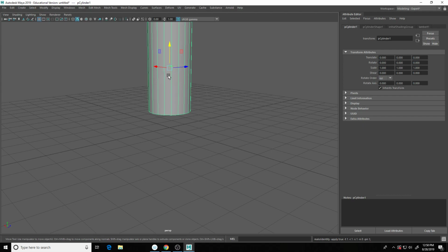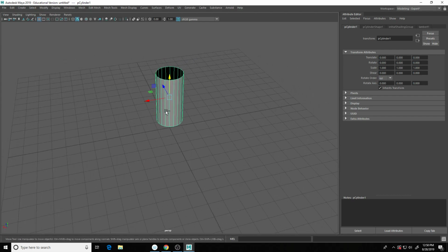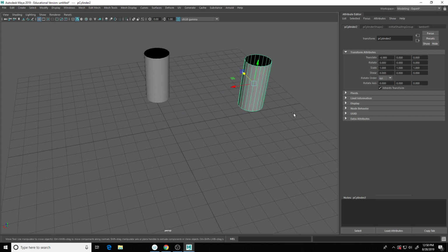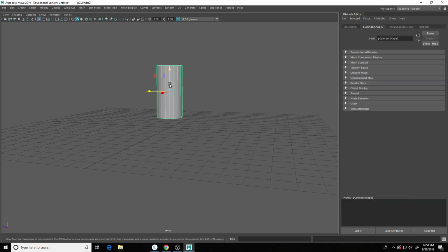This is at its 0, 0, 0 location every time I freeze my transforms. That's important if I want to, say, duplicate this, move one over to here, move this one over, and I need this one to be back in the original location. The easiest way to get it into the exactly same location is just to move it there mathematically. Does that make sense to you all? Freezing your location saves a lot of effort.